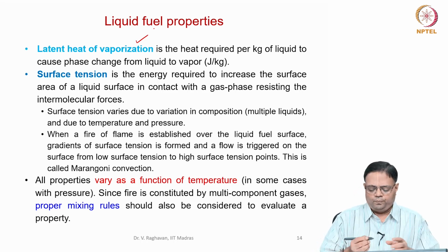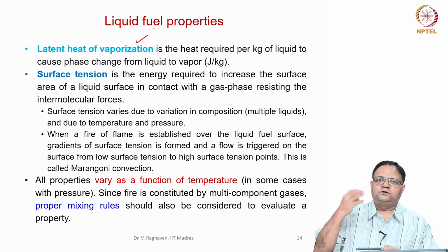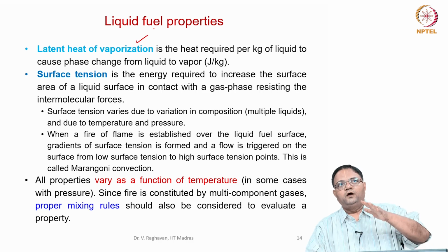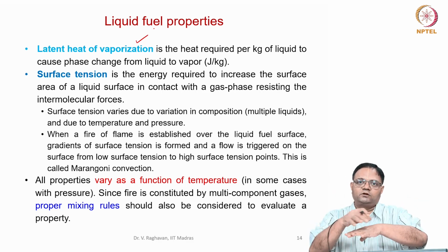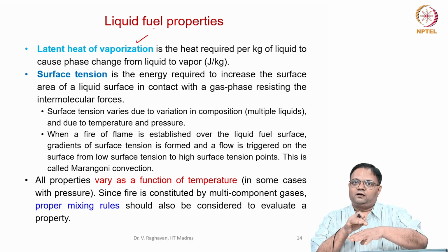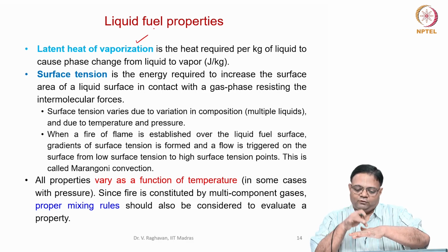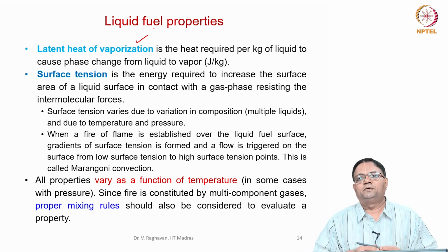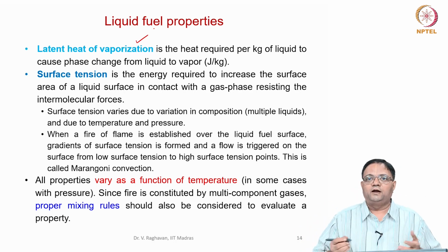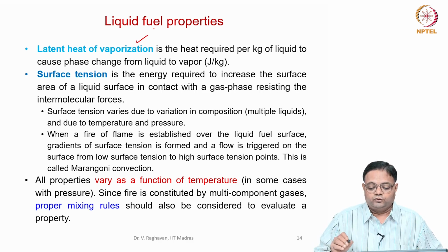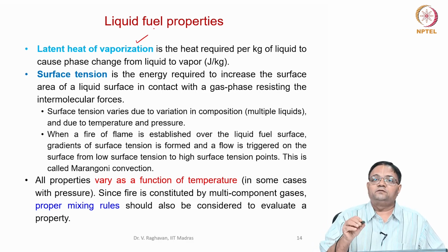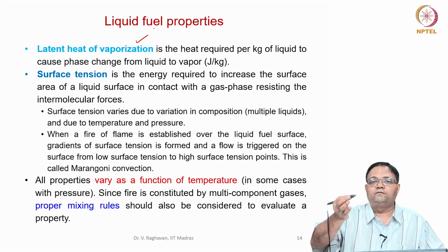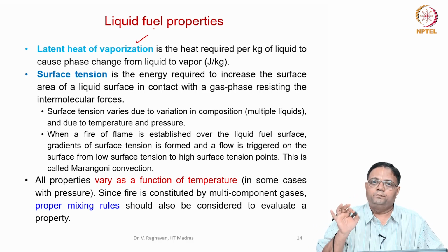Do you understand? So, basically you may wonder, saturation temperature, boiling point, it should be at boiling point? No, not necessarily. See, please understand that when there is a liquid surface and vapor over the surface, there is a vapor pressure which the vapor applies over the liquid surface. So, at that pressure, the corresponding saturation temperature is enough. Do you understand? That means I don't need to go to boiling point at all. So, latent heat of vaporization is the amount of heat which I have to supply to convert the liquid to the vapor at the particular pressure.